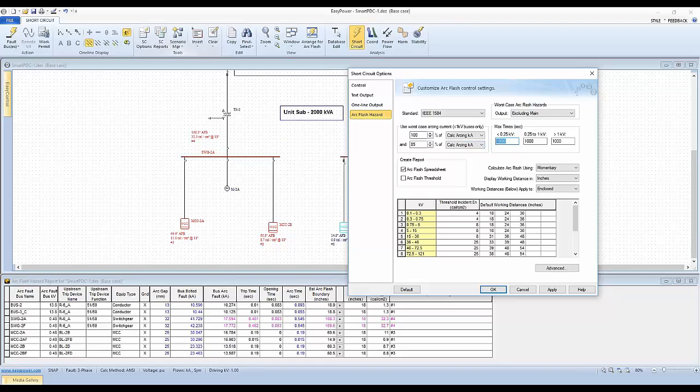What that recommends, and it's based upon IEEE testing, is that for 250 volts or less, you can actually get very long trip times if we have low current faults, low magnitude faults, and unrealistically high trip settings or trip reports from the fuse or the relay, the breaker that's upstream.